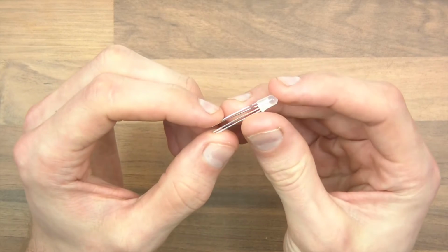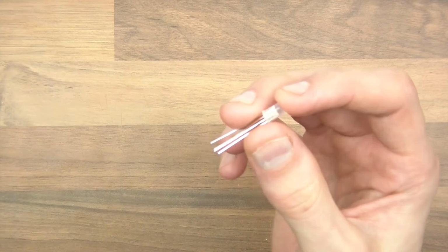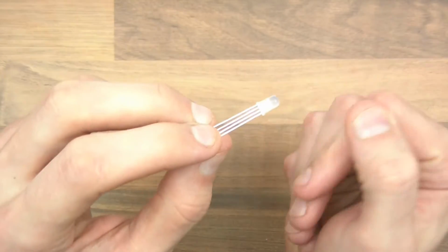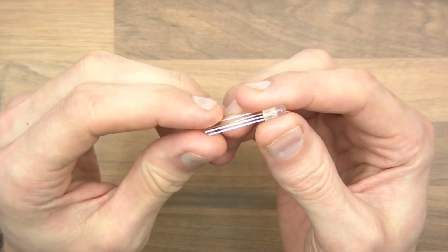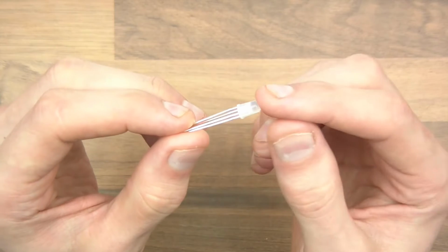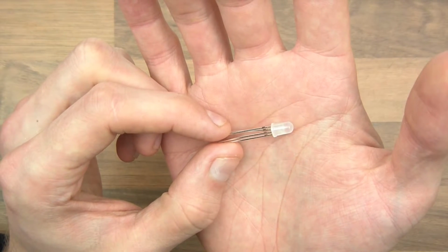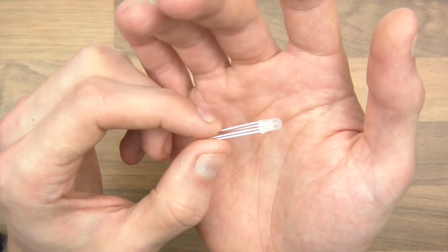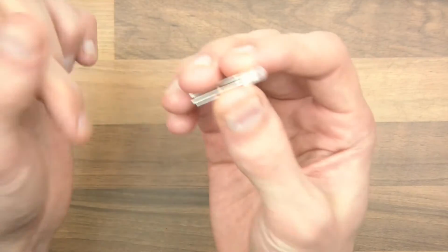So one thing that I see a lot online, and people sometimes ask me questions as well, sometimes I get emails and stuff: why do I need a resistor? Well, of course you don't always need a resistor. It depends on what voltage you're going to apply to the LED. And these have different voltages, and therefore if you've got a set power supply, let's say for example 6 volts, if you were to apply 6 volts to this, you'd kill it. It will just burn out.